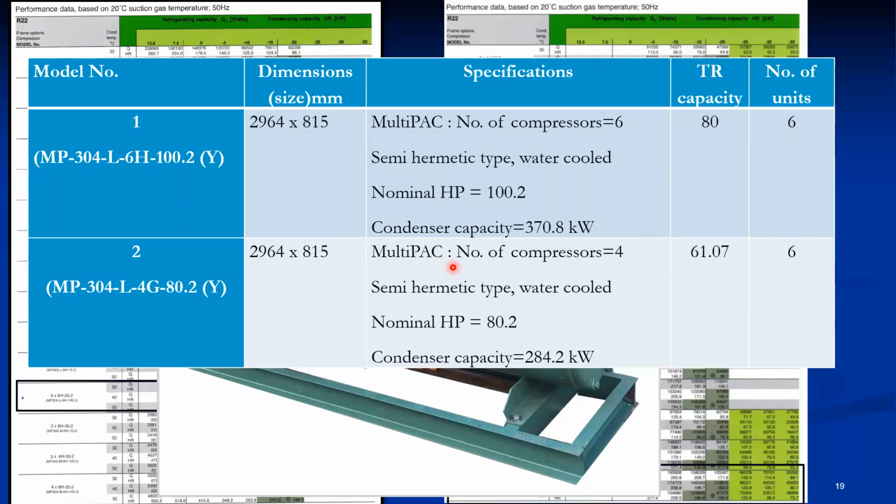So judicious selection of the models is also important because the major criteria are your temperature limits, -5 degrees Celsius, 40 degrees Celsius, then your cooling capacities. And that cooling capacity is further divided into multiple units. So 165 TR means 80 to 90 TR capacity is required. So that capacity is chosen. So 80 TR is our capacity, and here 100 TR, but 50 TR compressors are not available. So 60 TR. So this way the compressors are selected.